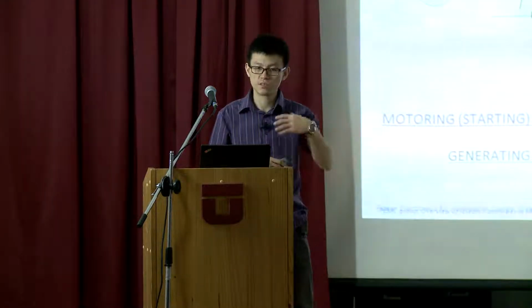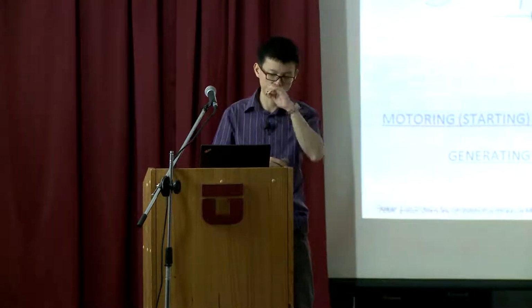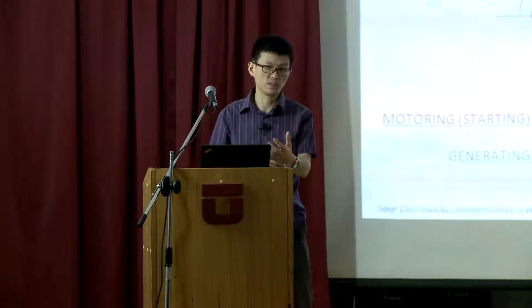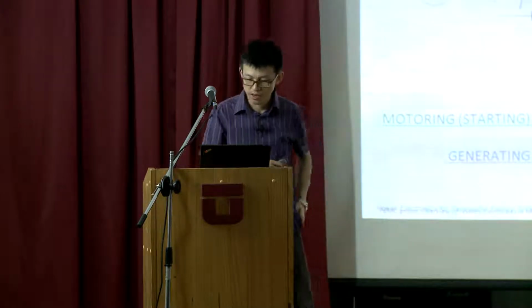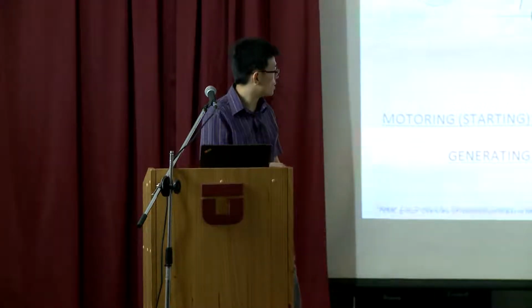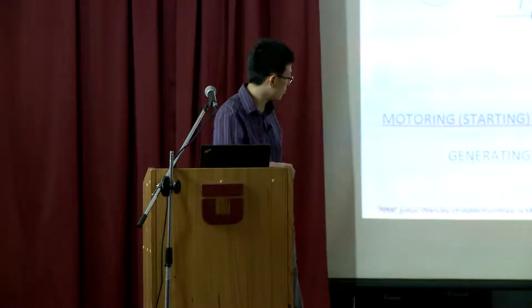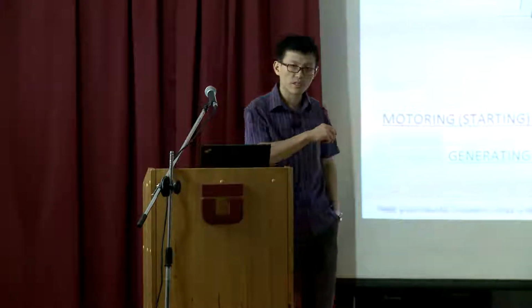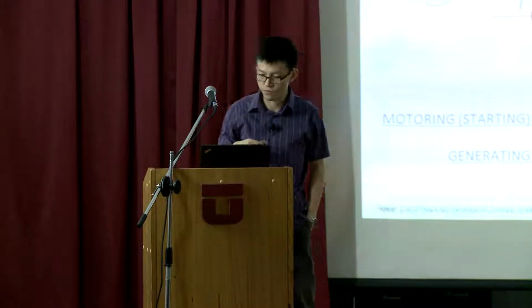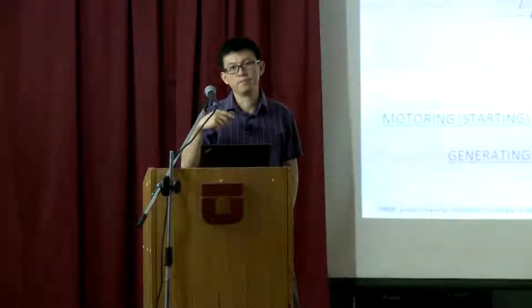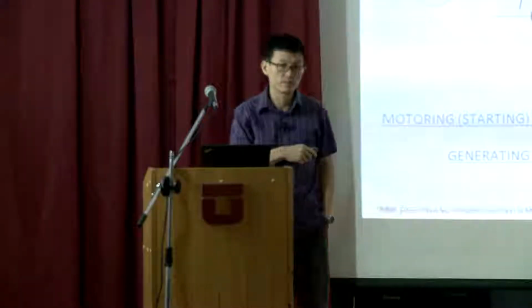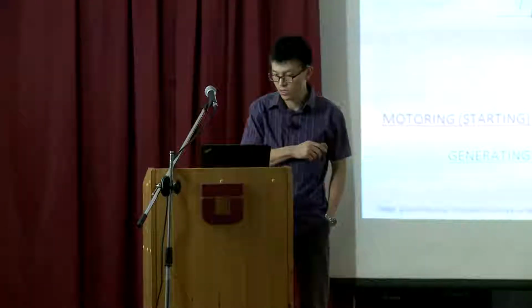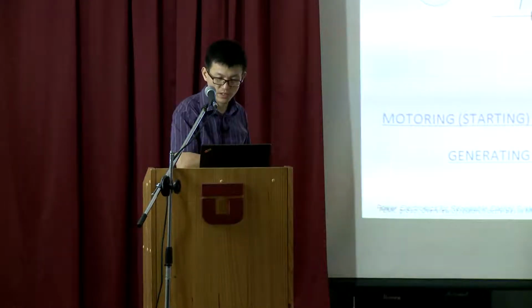We can use this machine to start the engine itself. That's why I call it a start generator. It's not only a generator, but also can run as a motor to drive the engine itself. But today we mainly talk about this functionality, generation mode, which means the engine shaft drives the electric machine and then supplies power to the load on the DC bus through this power converter. Okay.